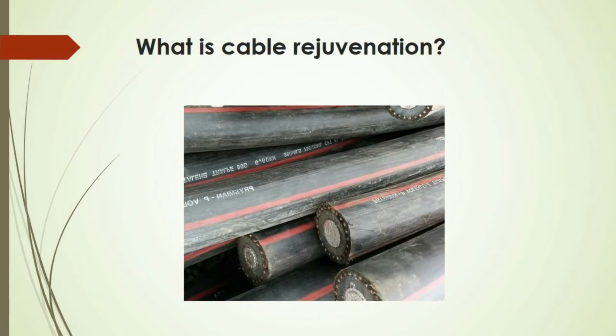Let us start off with the question, what is cable rejuvenation? Well, basically, we are restoring power cables. Silicone fluid is injected into the power cable and fills the strand region during cable rejuvenation. The fluid comprises a combination of components that heal water tree damage, inhibit new water tree growth, and in some situations update the cable with current cable ingredients.